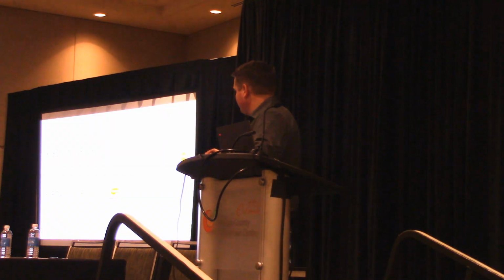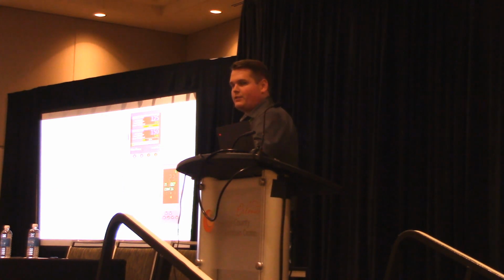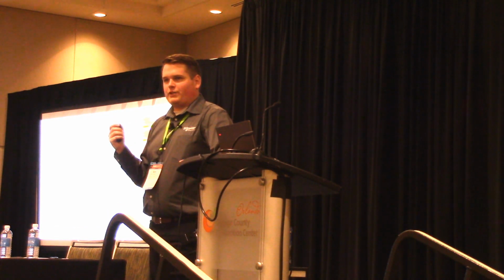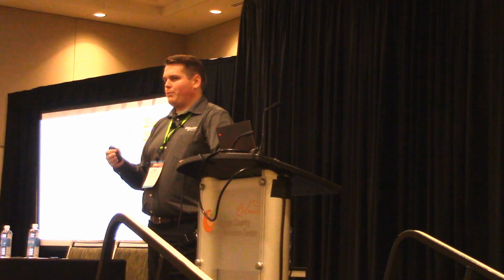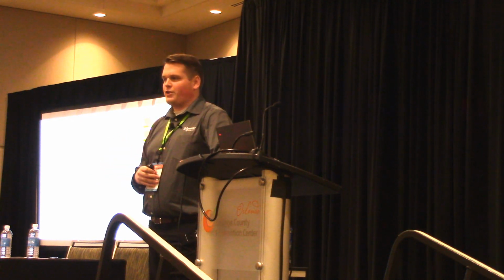What is that one metering, energy metering device? Top one there? So that's our Nanotech. It's a 2-loop PID controller as well as secure data recording. So when it's running, it's going to record whatever inputs are connected to it, whether it's flow, pressure, temperature, whatnot, to a secure file that can't be tampered with. We have proprietary software to open it with, free. There's no charge for it.